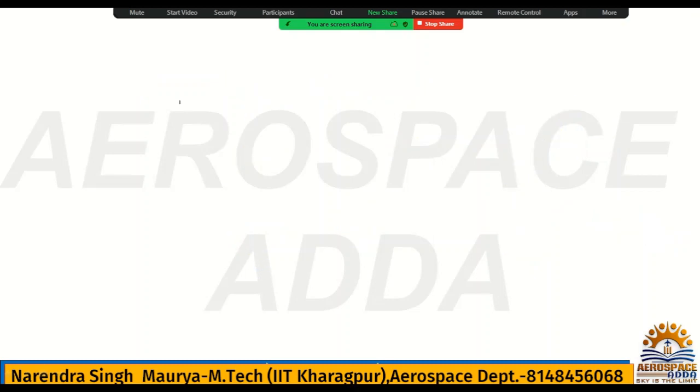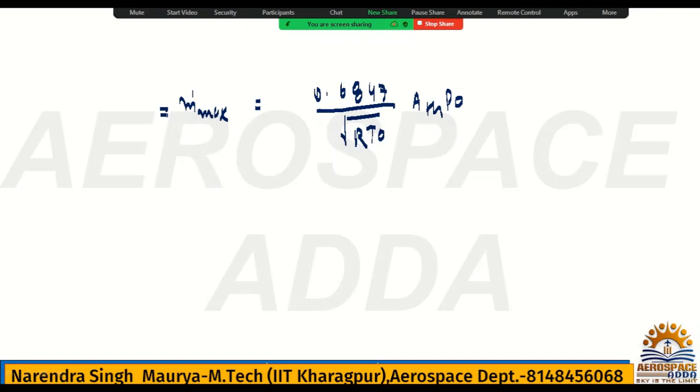We have the maximum mass flow rate formula, M max. What is that? It is 0.6847 divided by root of R T naught, throat area into P naught. Because this maximum mass flow rate you have just calculated, it is 19.04.